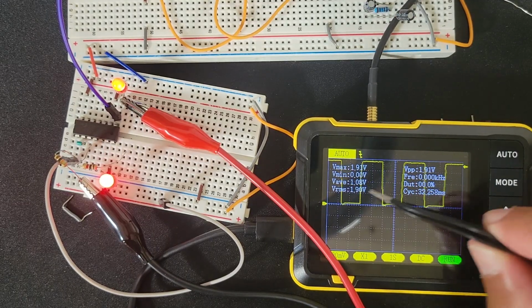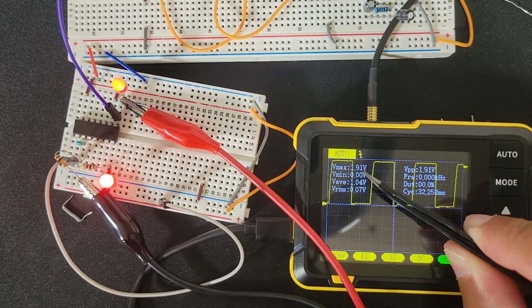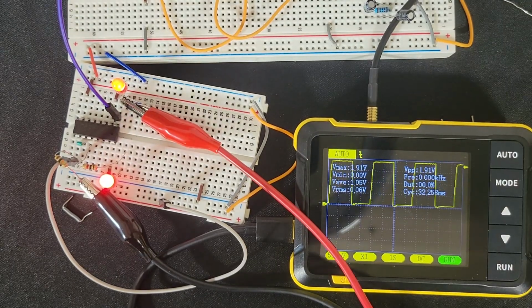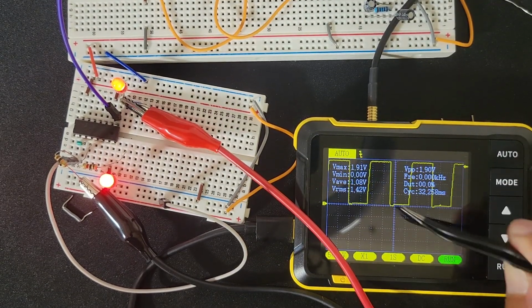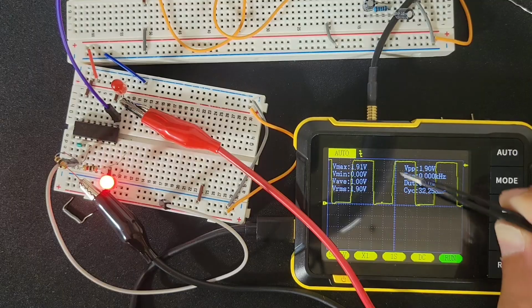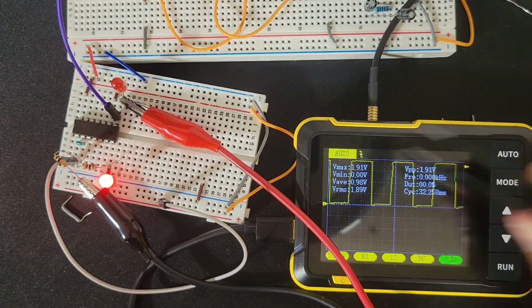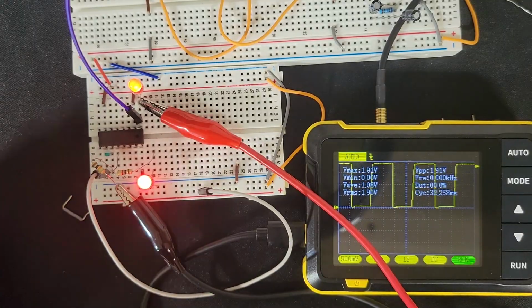Now, funny enough, I do see that the voltage is pretty low, 1.91. The max really should be 5 volts. I don't know why it would be so low. But man, that wave looks really beautiful. I like that. So we have a nice solid square wave, but maybe it's too weak to trigger the clock pulse on the shift register.